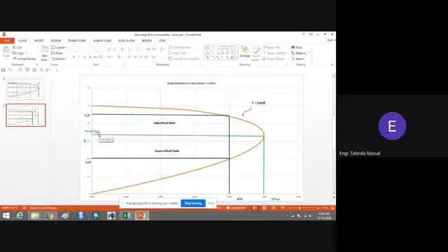If you remember, we developed this equation. And here you can see that if we bring this E here, YC divided by E is equal to 2 by 3, which is about 0.67, and you can see that this critical depth of the flow is about 0.67 or 0.7.